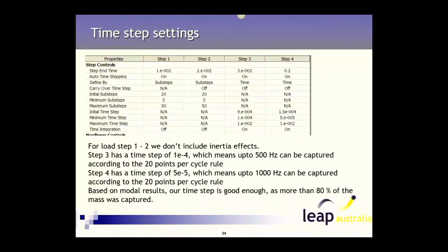In these steps you still need to use the same time steps to capture the dynamic response. But because we're not interested in that as we're moving the fingers down, it doesn't make any difference whether we include those effects or not, with the added benefit of a shorter time to solve those first two load steps.